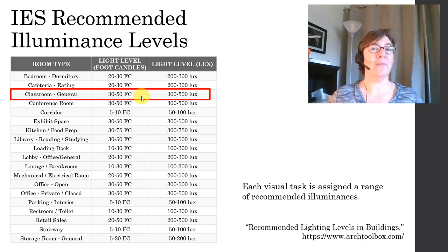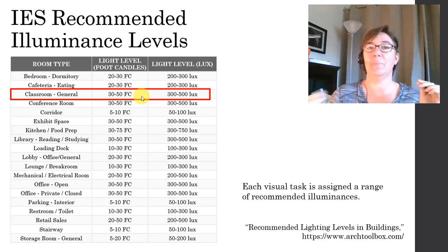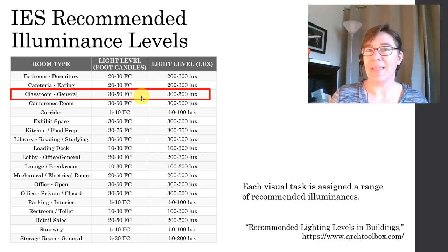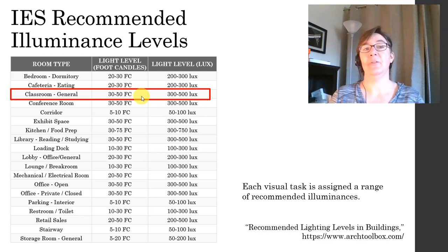And therefore, ta-da! Your proposed design with 12 luminaires of that specific type, and that mounting height and that specific lamp in there meets your target illuminance levels, you can check that box and feel good about your design.